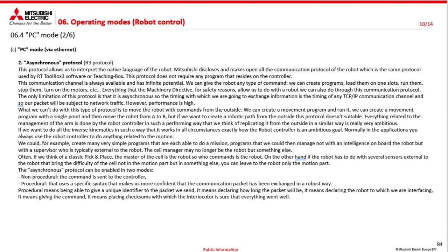This protocol does not require any program resident on the controller. This communication channel is always available and has infinite potential. We can give any type of command to the robot. We can create programs, load them into a slot, put them into execution, stop them, turn on the motors, and so on. Everything that the machinery regulation for safety issues allows us to do with the robot, we can do.